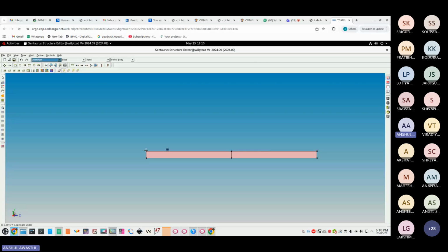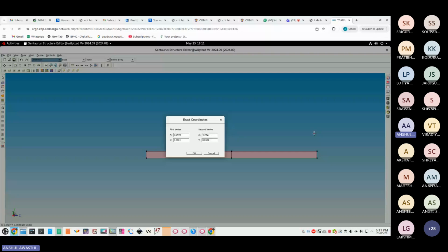So what I'll do, again, I'll make a rectangle anywhere. First of all, I define the contact where my P region is ending. So my P region is ending at 500 and the contact width should be 10 nanometers. So it should be 510. Now the width is the same as the N region and P region, that is 0.0 to 0.020.